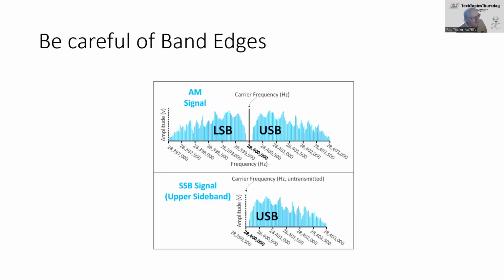Also, if your transmitter is not set up properly, instead of getting something like this, you can get a bigger, wider one. If you've got your deviation set too high, or your compressor, or your ALC, automatic gain control, not set up properly, your signal can be very wide. Also, if you yell into your microphone, it becomes wider and also more distorted.